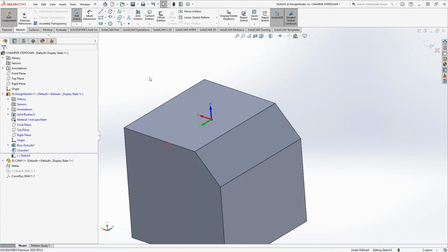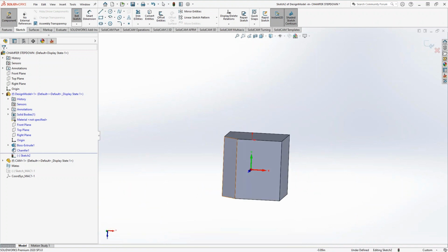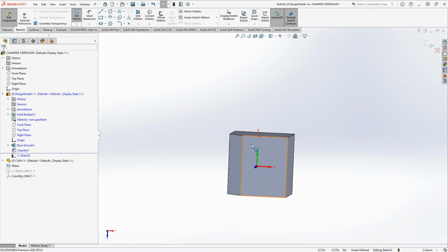Now, what makes translated surface difficult in a certain way is it's not just the sketching. The sketching can be easy because you know you want a path, you know you want to have your cross section, but where you put your cross section is the painful part, because it needs to actually be in the lower quadrant.